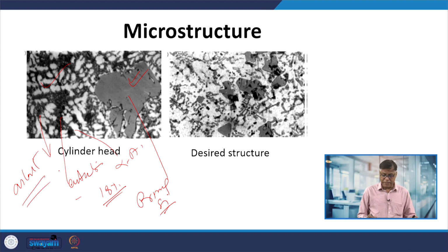Well, it was desired that the alloy should have been in the heat treated condition. So, the desired structure was that eutectic silicon should be fine and in the form of spherical particles, apart from a somewhat reduced size of the primary silicon particles. This is much more favorable in terms of reduced cracking tendency and increased resistance to crack nucleation and propagation.